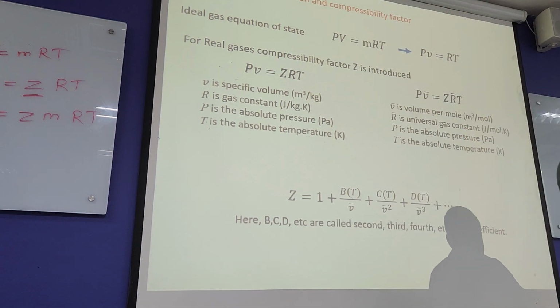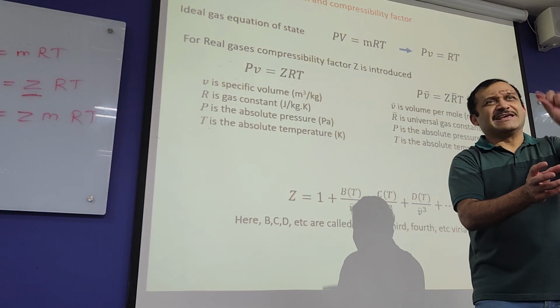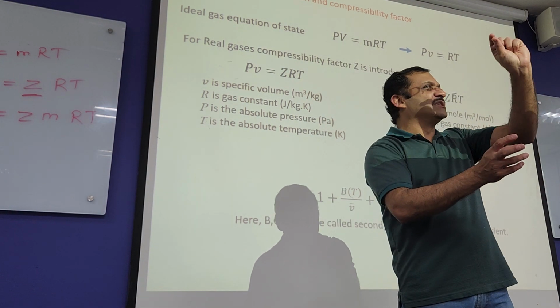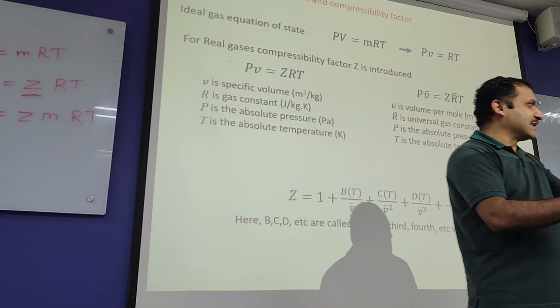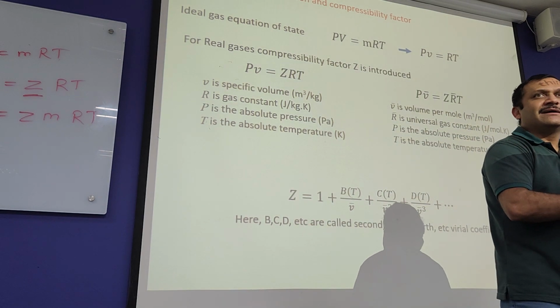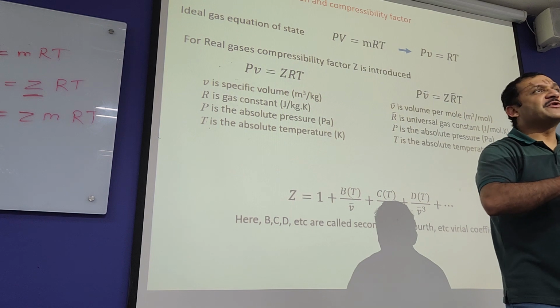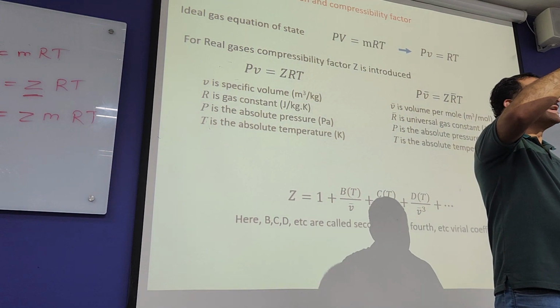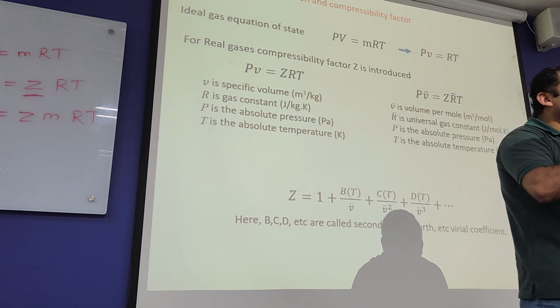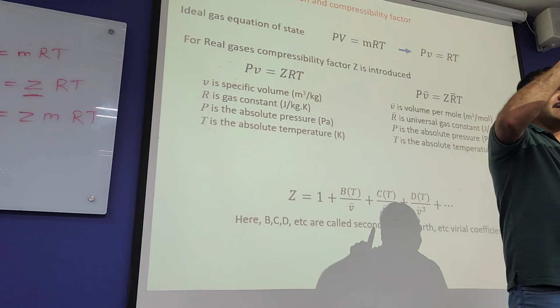Or you can change that experiment to a constant pressure experiment, which is a piston cylinder device with almost no friction in there. Minimum friction, or in theory a frictionless piston cylinder device. Same gas inside, start heating it up, pressure remains constant, now volume changes. For every half a degree temperature rise, you will get a small change in volume. You record that.